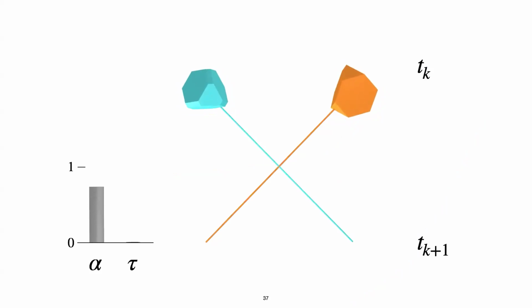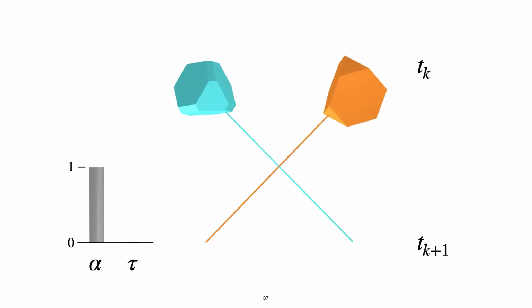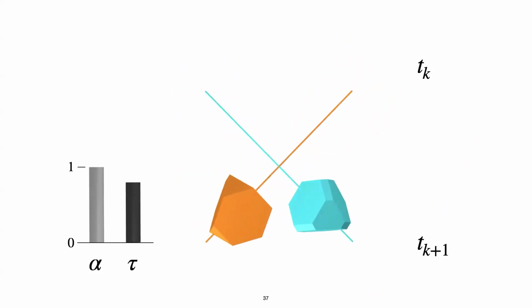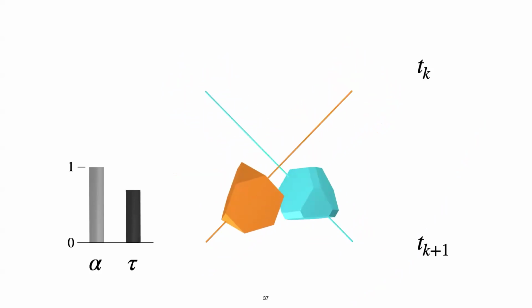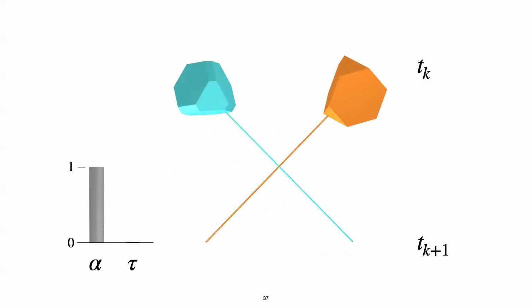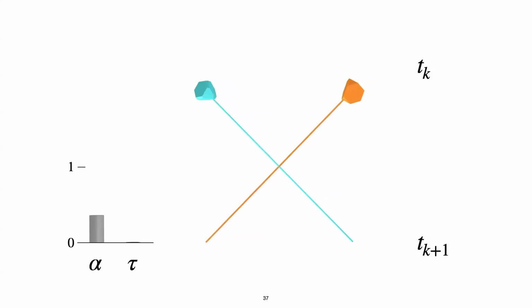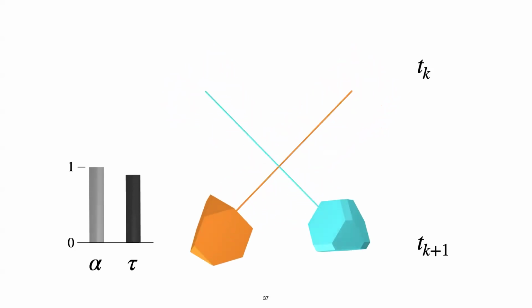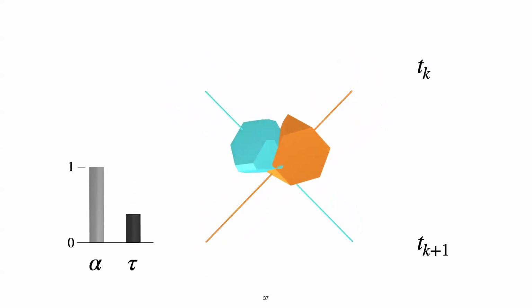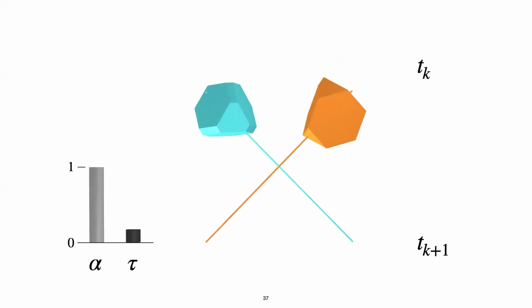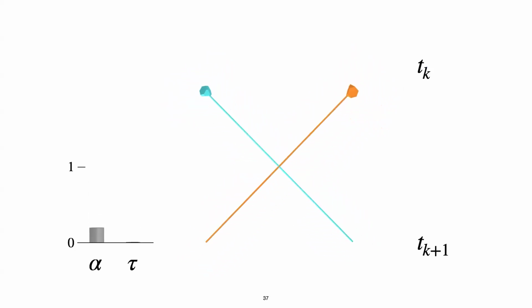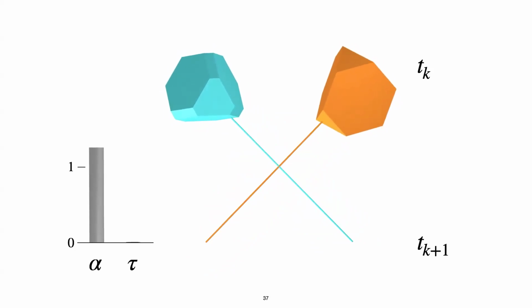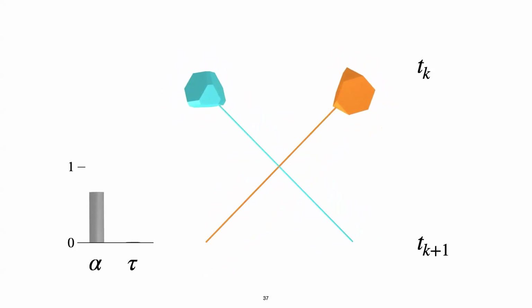So now if we think about this in an optimization, uniform scaling-based framework, I now have 2 parameters. I have alpha that will inflate these things up and down, just like before. And then I now have this tau parameter. And tau is going to slide these objects on a track between time step k and time step k plus 1. So what the solver can do is wiggle both alpha and tau. They can figure out what is the minimum alpha that results in a collision between these objects. And in this case, we can see that if I check the collisions at both knot points and just look at those knot points, they're not in collision, but obviously they're passing right through each other. So we should be able to identify some collision.